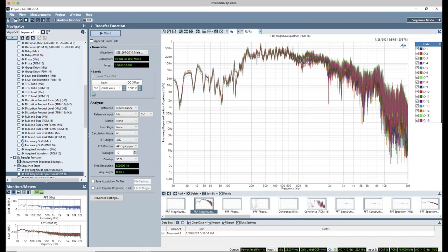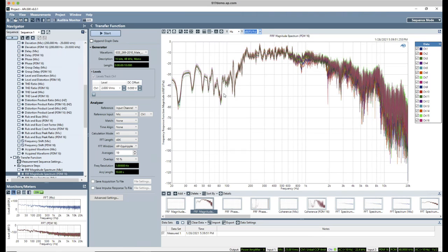And now that I have done that, I realize this looks a little noisy because I'm looking at 16 results with some quite high resolution. But here is our frequency response. And because it's relative to that analog reference microphone, it's dBFS per Pascal. So we're looking at the digital audio signal coming out of the MEMS microphones in relationship to 1 Pascal of sound pressure.